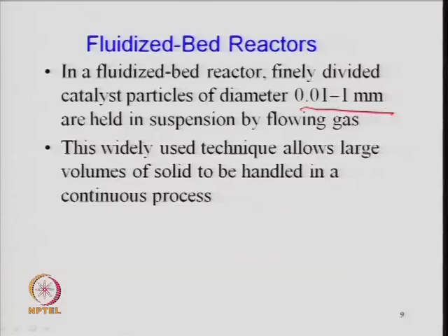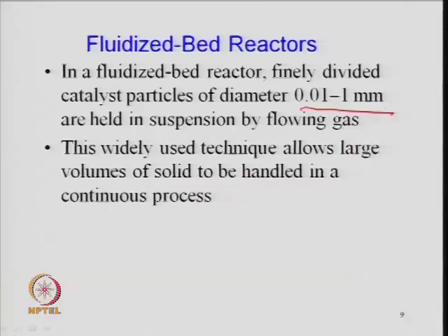But as I said, fine powders are used, and small particles will fluidize better. Generally particles of the order of micron, 50 micron, 100 micron, are used for this purpose, especially in catalytic cracking. The idea is that the solids behave like a fluid. They are in the condition of a fluidized media, suspended in the column or in the bed by a flowing gas.